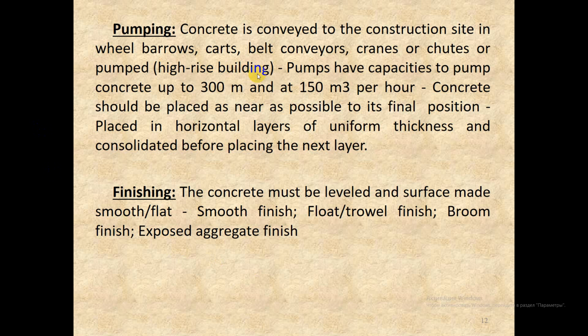Pumps have capacities to pump concrete up to 300 meters and at 150 cubic meters per hour. Concrete should be placed as near as possible to its final position, placed in horizontal layers of uniform thickness and consolidated before placing the next layer.